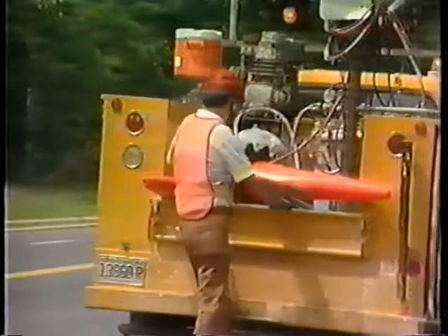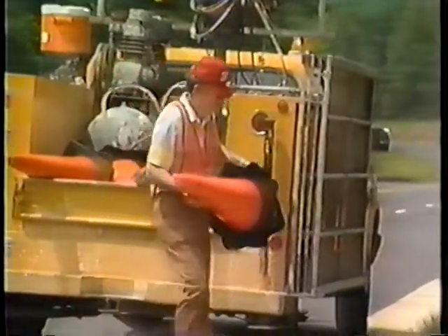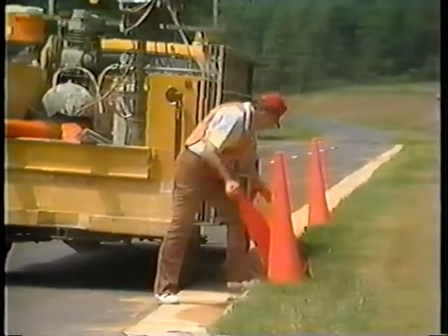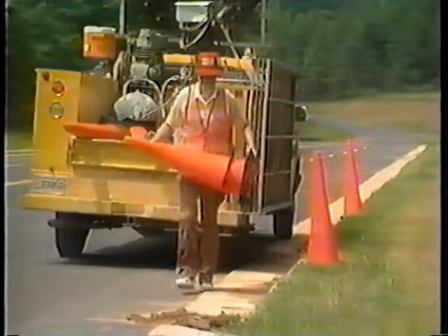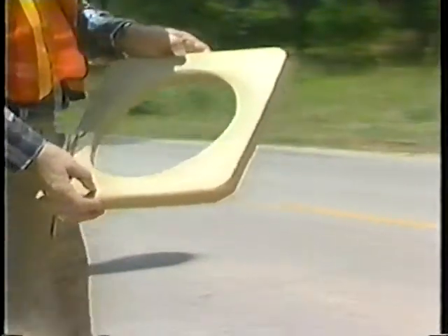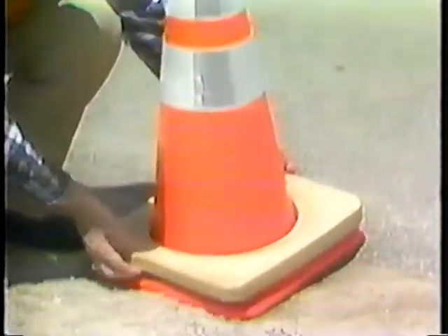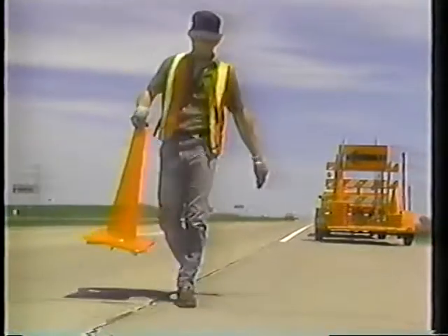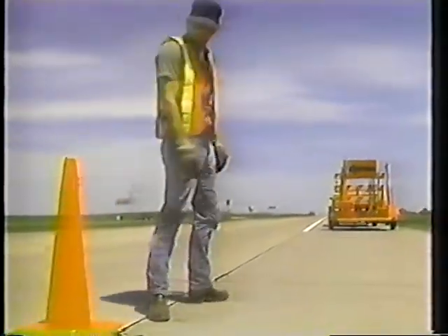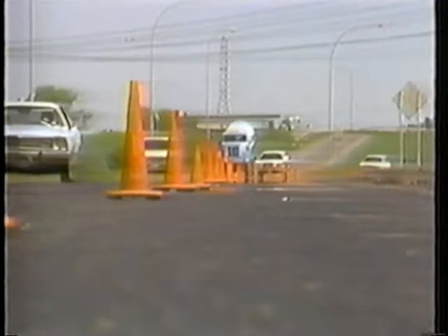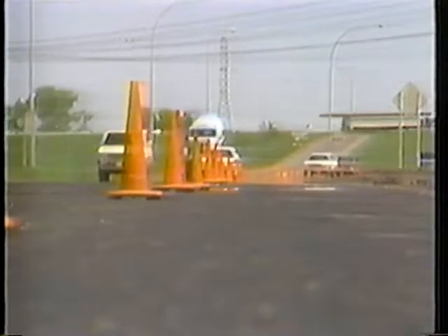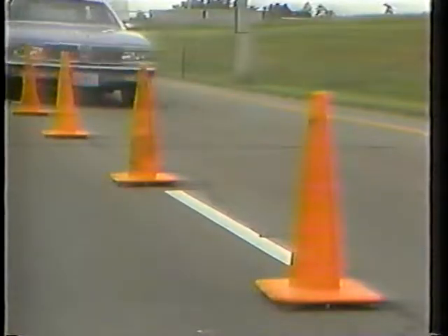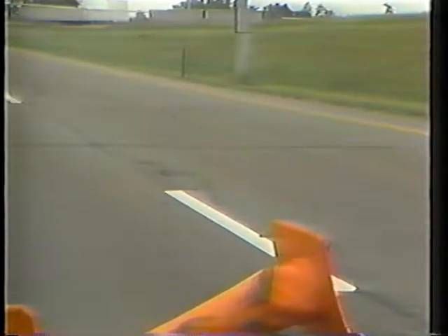Cones are lightweight channelizing devices that may be stacked for storage. They are easy to place and remove and are a minor impedance to traffic flow. For stability, a rubber or sand collar or a specially weighted base may be added. When purchasing cones, specifications may require 60% or more of the weight in the base, thus removing the need for extra base weights or collars.